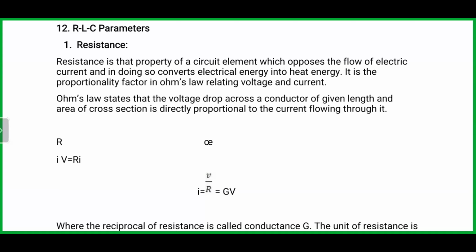We hear that it's not good, it's not safe. As fire safety people, we know that if there's a loose contact, there is friction in the cables which causes heat. The heat burns the insulation, and if it touches any combustible materials, it ends up in burning. That is where fire starts from, at the electrical aspect.